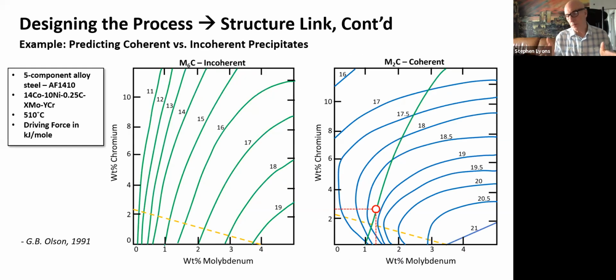So is the martensitic quality or degree a function of how these materials cool? Because blacksmiths have been cooling in water for like 3,000 years. And then the Japanese discovered that you can cool in oil, and that cools more slowly, and that affects the martensitic quality. Is it the medium that you use that controls the martensitic quality? Yes, if you cool too slowly with certain alloys, you'll go back to ferrite, which is weak and soft. So you've got to cool quickly.